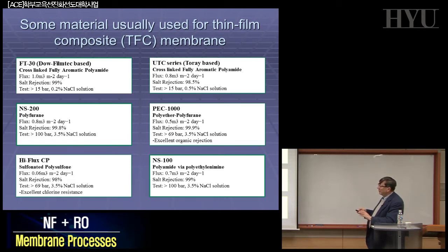And also in this case, however, when you have a characterization of your membrane, you are always supposed to give in which condition. These numbers are not universal. These numbers are always much related to the fact that you have been working with a 0.5 molar solution at a certain temperature, at a certain pressure, etc. Because it's not easy to transfer from one solution to the other. First approximation is possible, but depending, you can have compaction phenomena changing the pressure, for example, and you can have some difference related to the way in which you've been making the characterization. So when you make a test, when you give some numbers, it's always useful that you know in which condition these numbers have been produced. So you will find always the condition of reference, basically.